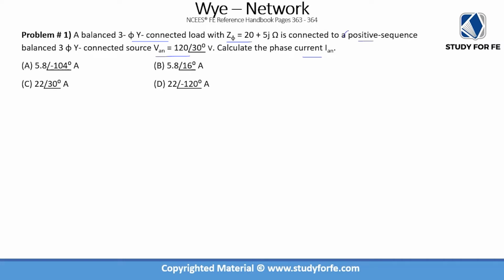Don't worry about the positive sequence over here, because that is the general nature of the system when it is balanced and operating fine. It is a concept that we discuss in quite a bit of detail in the PE power exam preparation course. But other than that, what you have to focus on is the impedance that's provided to you, the fact that your load is Y connected and the source is also Y connected, and you are given the phase voltage and you are being asked to calculate the phase current.